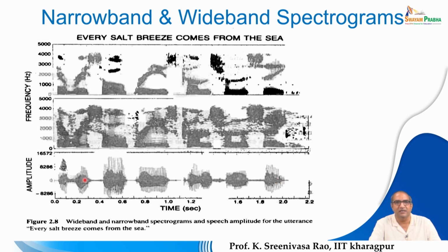If you look here, there is a gap here, and here, and over here. These gaps correspond to pauses. And before this voiced signal there is some random fluctuation, and here also before this voiced signal, and here also there is a random fluctuation. All these random fluctuations are due to the unvoiced speech.